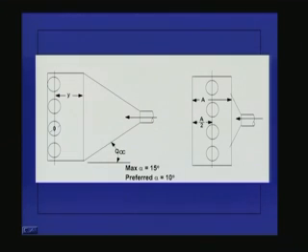A typical design for a pump sump is like this. This is my inlet pipe to the sump. This is, let us say, coming from the intake structure, and we are operating 4 pumps in parallel. The sump should be designed such that the flow approaches all these 4 pumps more or less uniformly, and a single pump is not stopped. Sometimes we may have 4 pumps, but we may be operating only 2 pumps. In such a situation also, the flow should be approaching these pumps more or less uniformly.